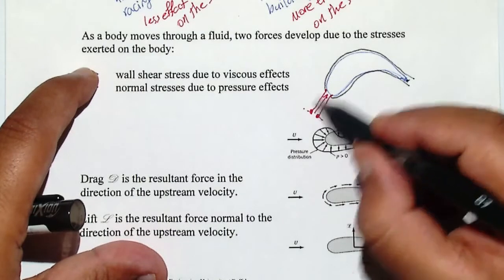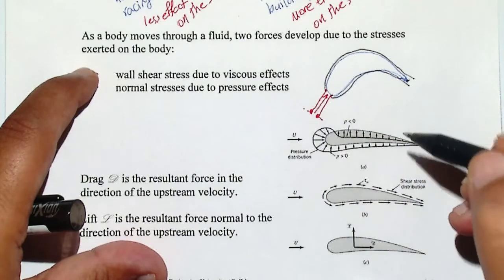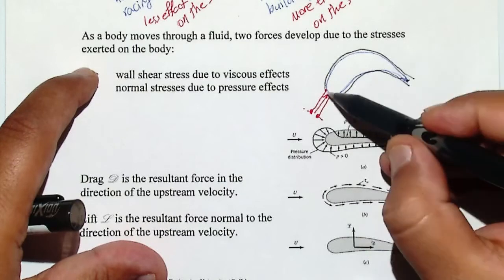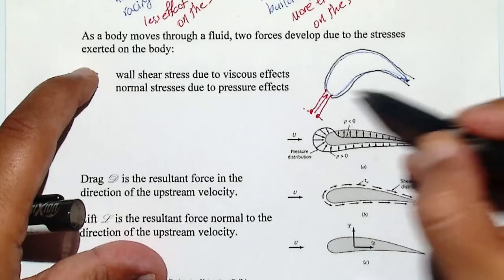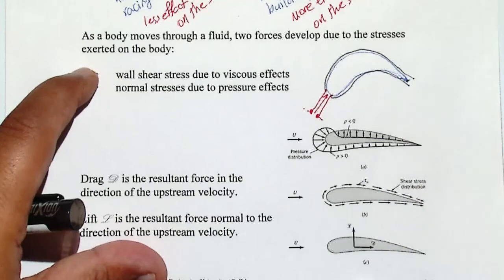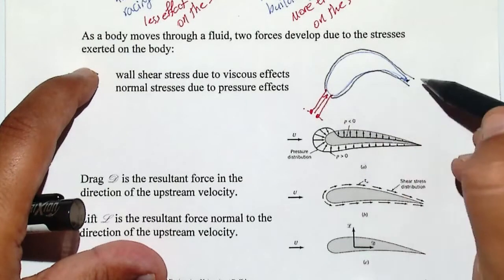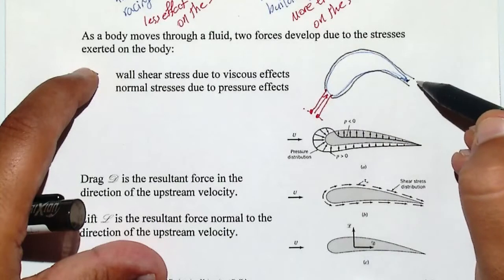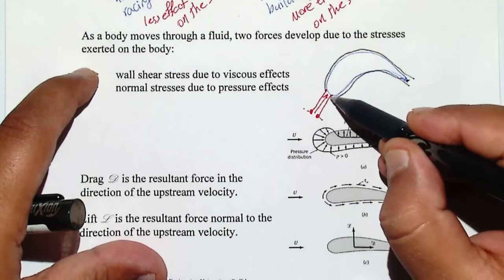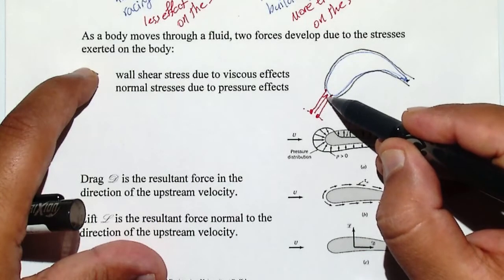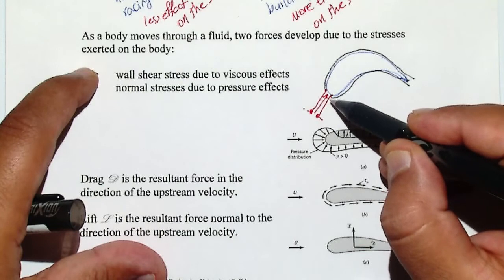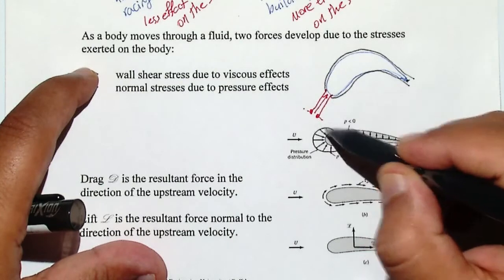So for these two, based on Bernoulli's equation, the static pressure in both is atmospheric pressure, and you can assume that Z is not that much different between these two. It means that the 1 over 2 rho V squared, or V squared over 2g, is going to be equal for these two elements, right?